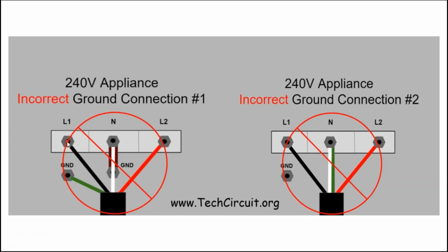Now, there are other forms of improperly connected power cord connections, such as a neutral connected to L1 and an L1 connected to neutral. But in those cases where you have L1 and L2 that are misplaced, oftentimes the appliance will show symptoms that indicate that there's an issue.